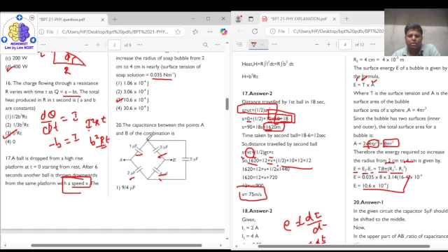Now because the ratio is the same, the potential between this point and this point will be the same. There will be no potential difference. Therefore there will be no charge, or you can say no current, flowing in the 5 microfarad. Therefore the final circuit between A and B would be like this. So this will be your 1 microfarad, this will be 3 microfarad, this will be 2 microfarad, and this is 6 microfarad. Because they are in series, it will be equal to 3 upon 4, and because these are in series, it will be equal to 12 upon 8.